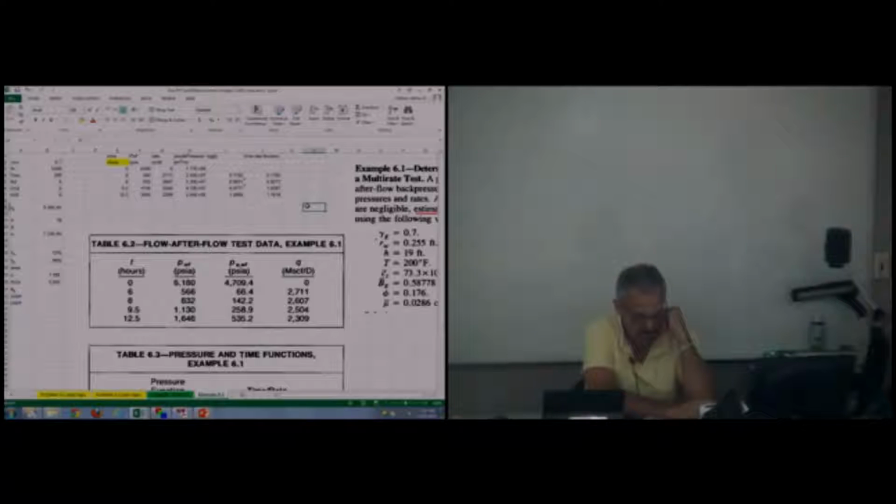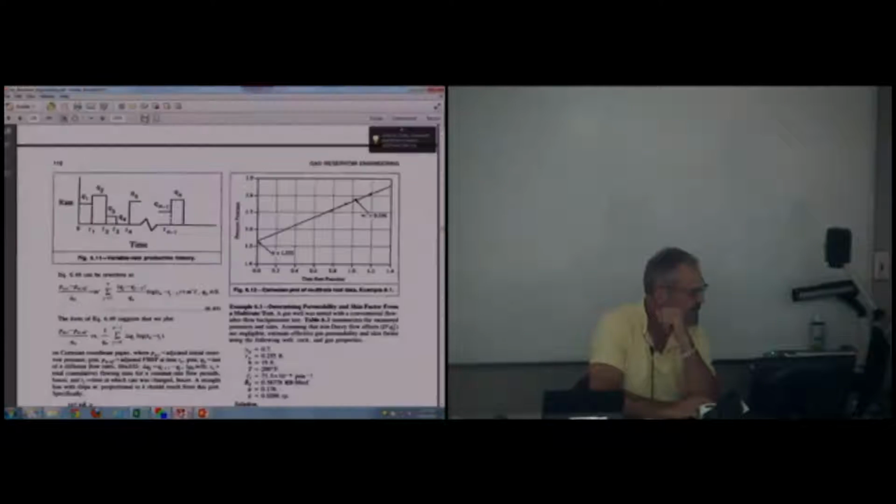Is that what we just did there? Is that supposed to be a full representation of equation 6.49 or just a part of it? It's the summation. We are going to cross plot a delta pressure divided by rate. We almost have those terms in our... Oh, okay. That last term's outside the summation. Yeah. Okay. And then what we're after is the slope of that straight line. Once we get the slope of that straight line, that's going to be proportional to permeability.